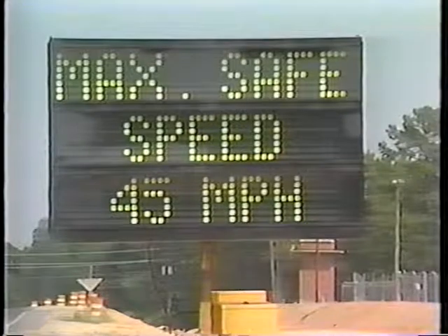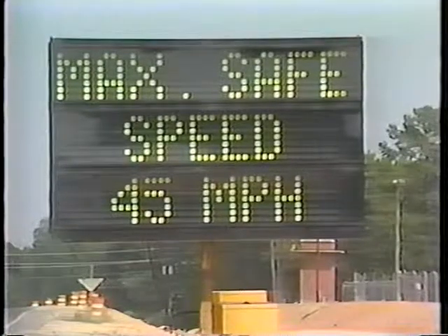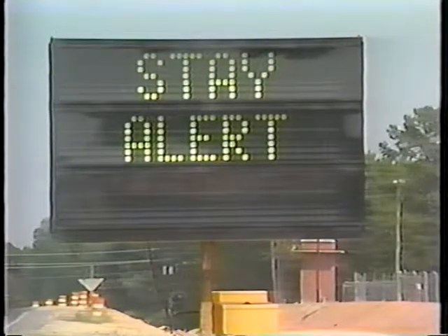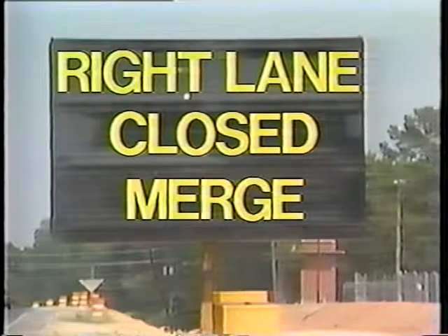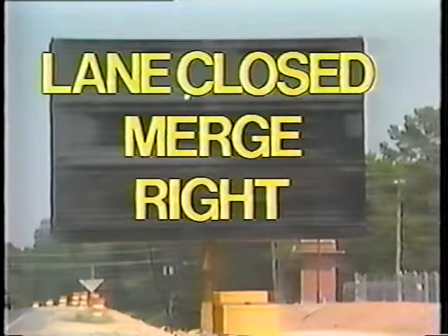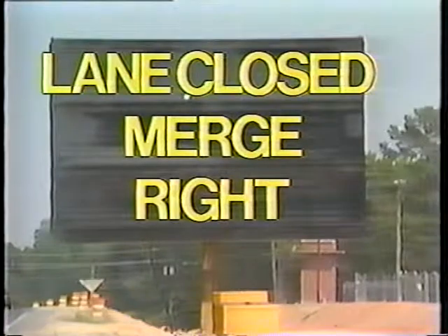When using a changeable message sign, be sure the message is clear. A lengthy message may distract the motorist too long. The word order in a message can also cause problems. For example, right lane closed, merge would get a different driver response than lane closed, merge right. Yet the messages are similar, except for the beginning point.